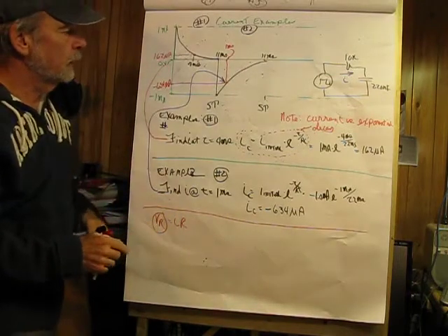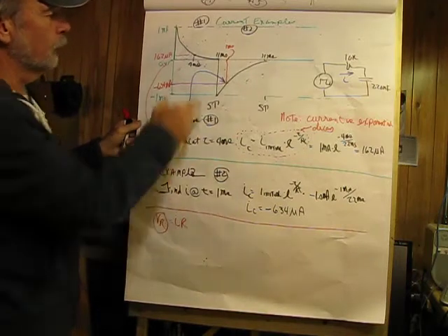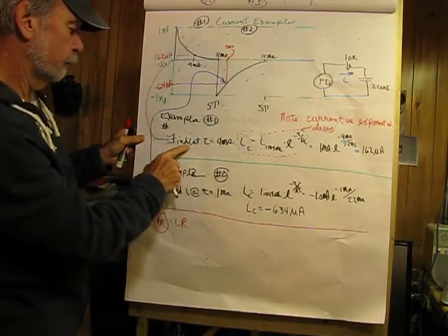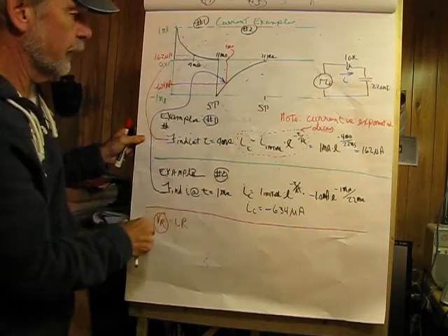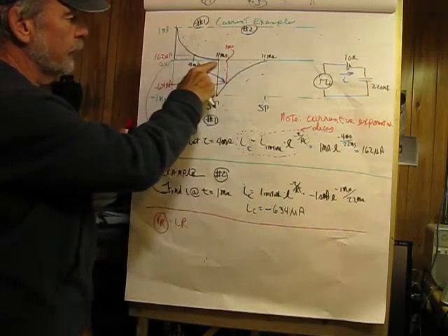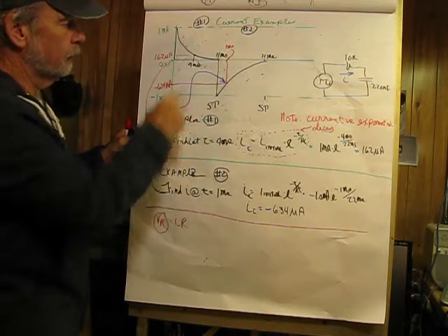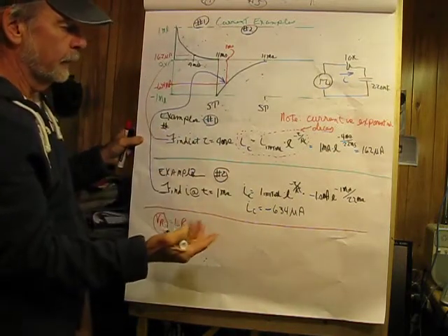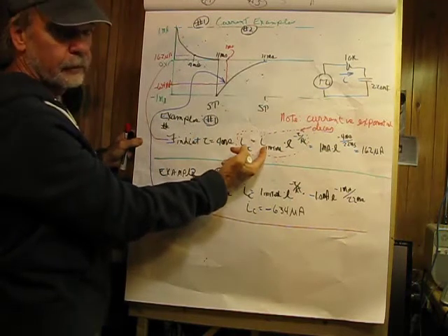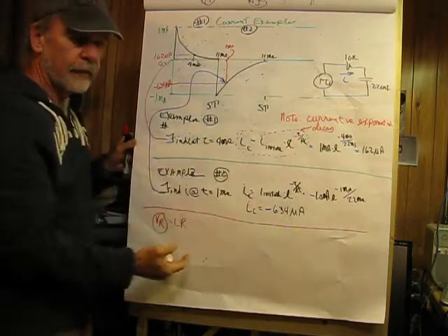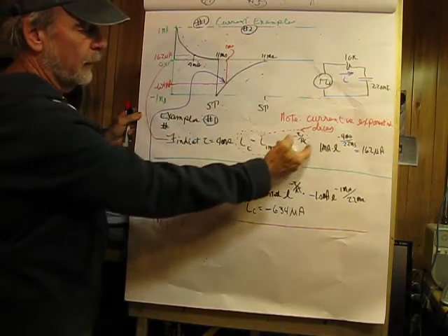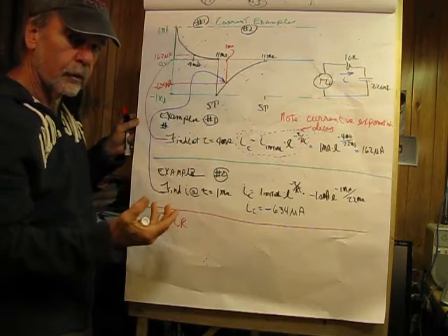Okay, current example, and then that'll be the end of part 1 here. I'm going to analyze this as part 1 again. And what we want to do is find I at t equals 4 milliseconds, and the current here is going to be an exponential decay, and I've not put the actual voltage in here to simplify things a little bit. And since this is a decaying exponential, we have the simpler formula of I initial times e raised to the negative t over time constant. So again, the initial is going to be multiplied by a value that's getting smaller and smaller and smaller.